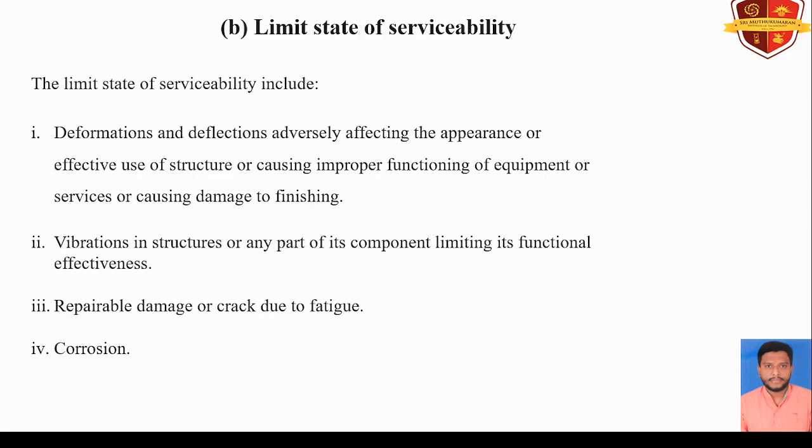Next one is limit state of serviceability. It includes deformation and deflection adversely affecting the appearance or effective use of the structure, vibration in structures or any part of its component limiting its functional effectiveness, and repairable damage or cracks due to fatigue and corrosion.